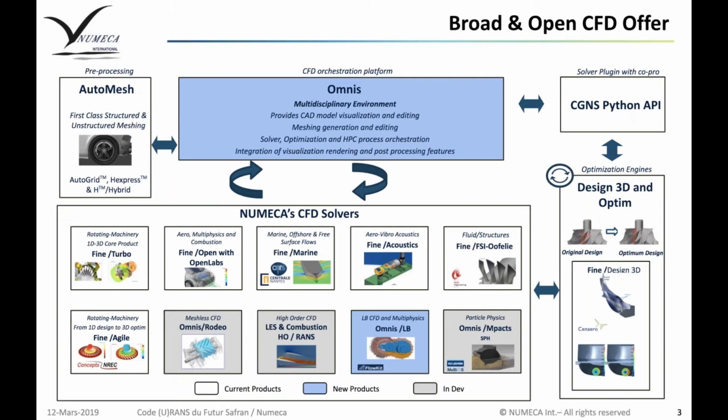And you need to be able to change your geometry and have the CFD run smoothly without the need for the user to intervene, change the mesh template, or find a solution if the solver fails. Because if you have to do these types of things, then the process will be very difficult to be successful. So that's something we always kept in mind when developing, and it means also having everything possibly run in full batch from A to Z.